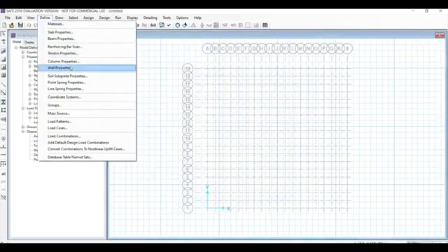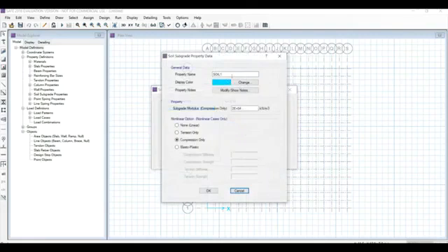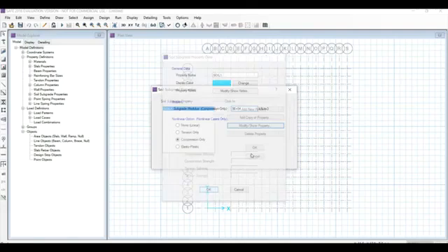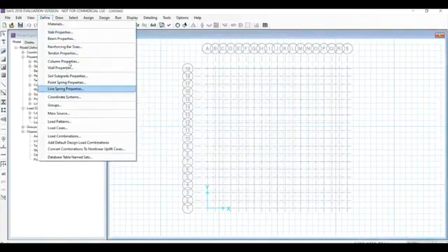And now define the soil subgrade properties. Let us assume about 30,000 for the soil subgrade properties, and modify the soil subgrade property. Here we have 20,000, so make it 30,000 by changing it here to a 3, and then click OK. Click OK, and then the define column properties is completed and the soil subgrade properties are also completed.